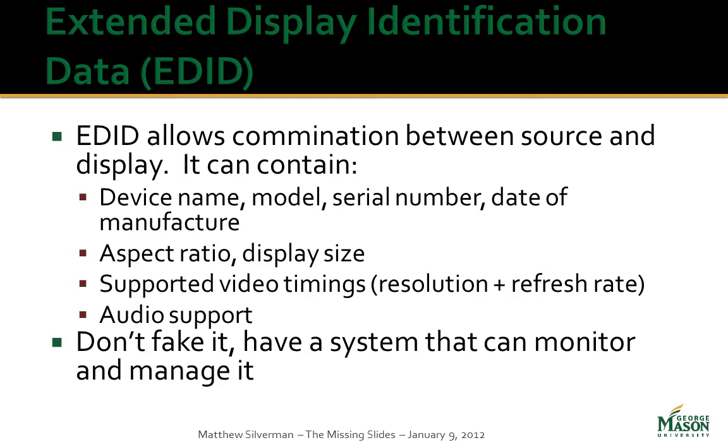When we looked at EDID in our environment, we really had to define what we supported and what we didn't support as far as resolutions, display ratios, aspect ratios, and those sorts of things. There are so many different computer resolutions out there that it's something we had to look at. The real big thing I'll throw out with EDID is that you need to be aware of it. You need to understand how to read the data in your system.